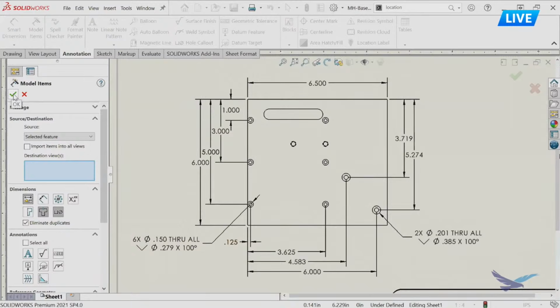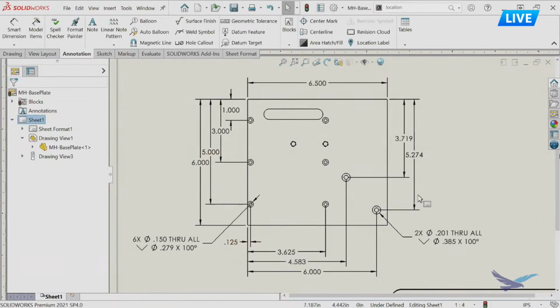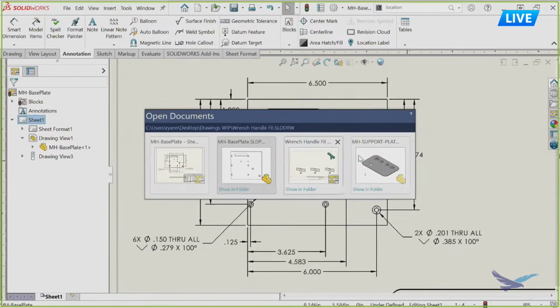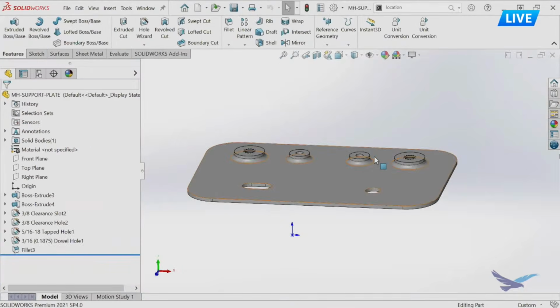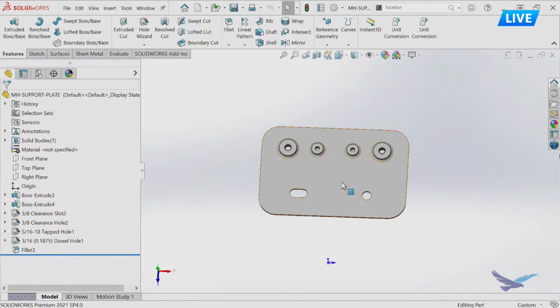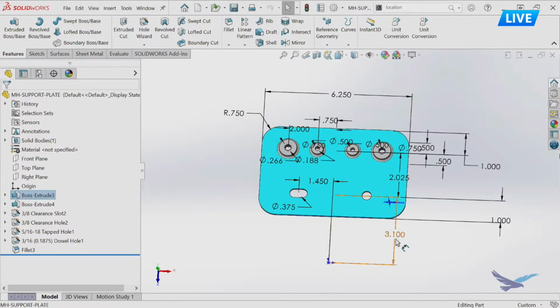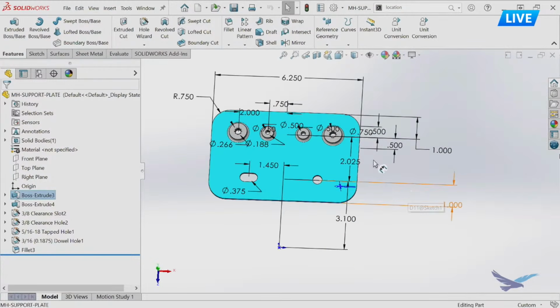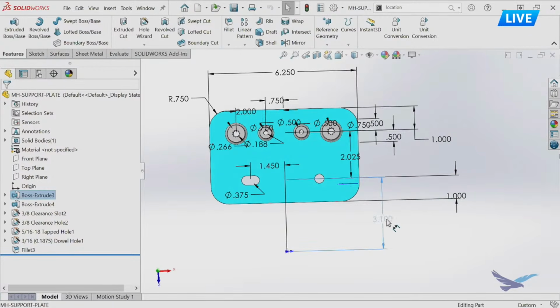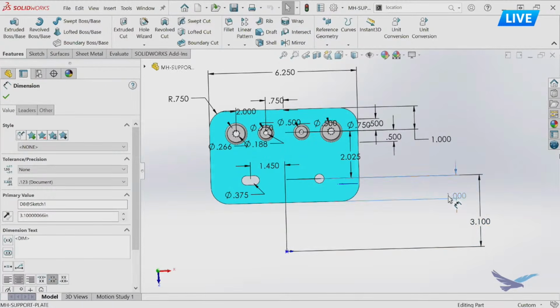Now, there are some other considerations with it, which are that you need to have the dimensions there. So if you have a part that's designed, let's say in context in an assembly, you may not even have that dimension information, or you might have too much dimension information. You might have dimensions to references that you don't want. This was designed in an assembly, and so it's got some dimensions that kind of point off to space, to some offset origin, or you might have master sketches that have things that aren't going to import well over to your drawing sheet.